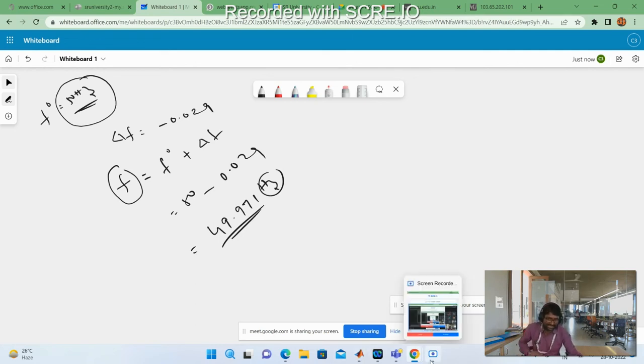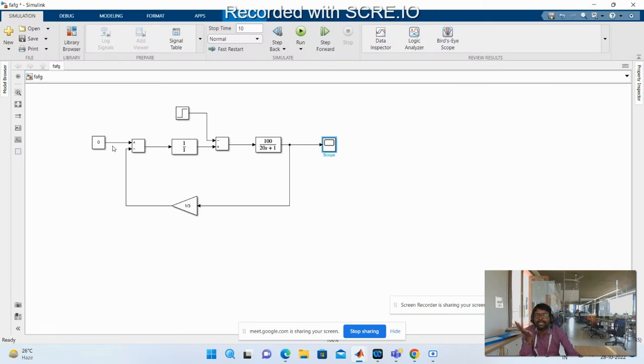This is a subcase. This is case 1, first order free governing operation. Why is it a first order free governing operation? Because delta t is equal to 0, it is a free governing operation. And the first order approximation is obtained by choosing KRG into KT equal to 1, TRG equal to 0, TPS equal to 0. That's why it's called a first order approximation. In the first subcase, the load is increased by 0.01 per unit, so your frequency decreases and your delta F will be on the negative side.